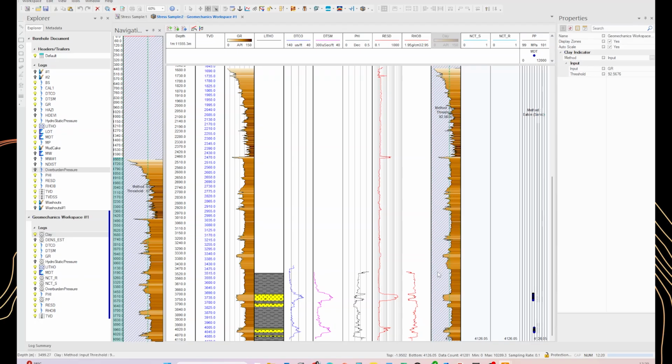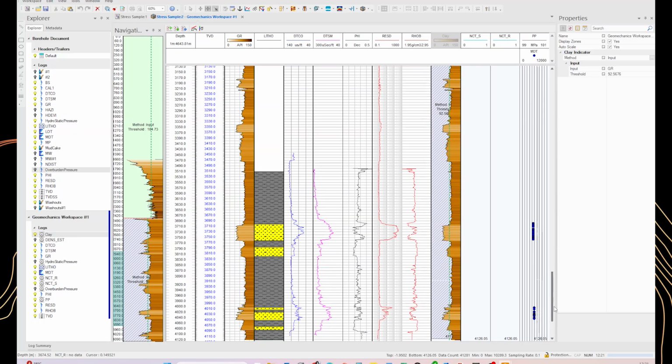big packages of shales. But as you can see high up, there is a change in the regime of the rocks. So we will create another zonation so that we can put a different threshold for the shales. We can zone into the area of investigation, which is the lower section of the borehole where we have more data. And we can be more specific with this threshold, moving it a little bit to the left, around 87 API of the gamma ray.